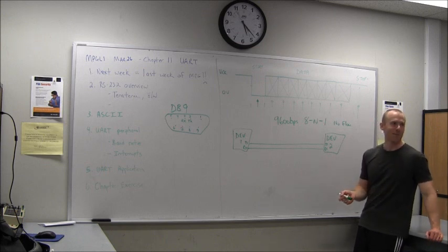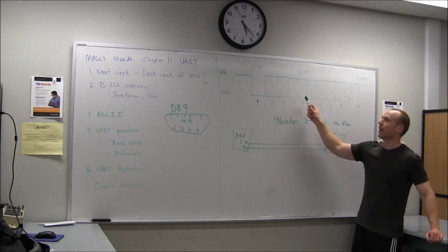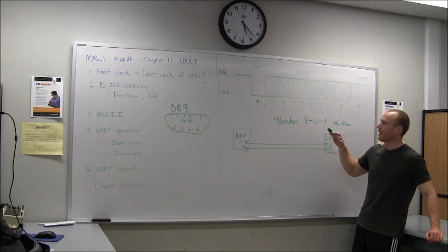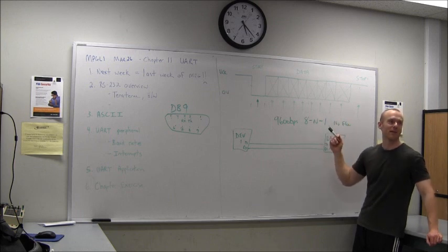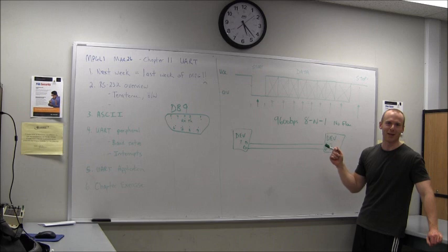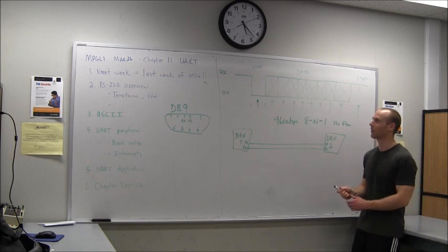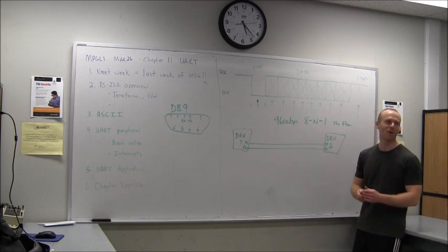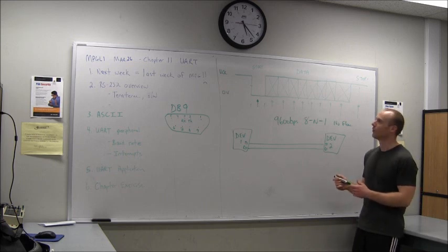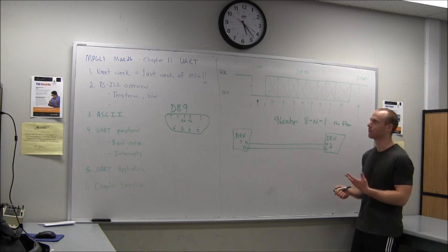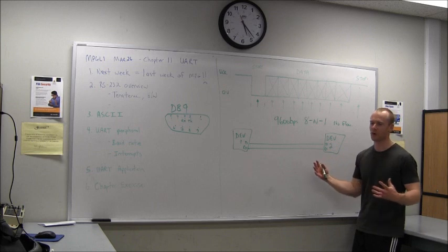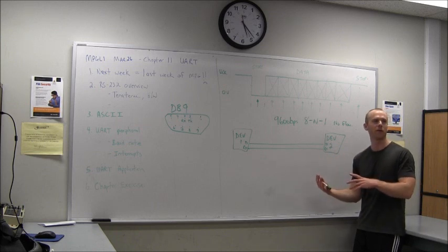Now, lots of problems here. Data bytes, you don't know if they're high and low. Without any built-in error checking, there are so many problems that can occur with this that you might think it's a very unreliable protocol, but it tends to work quite well. If you need to add some robustness, then you tend to add your own things, and usually you do it within the messaging protocol that uses a UART transmission.